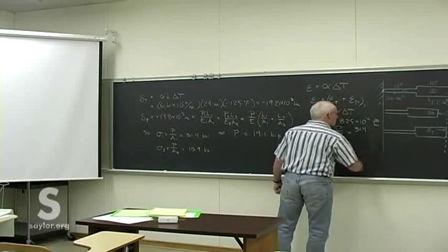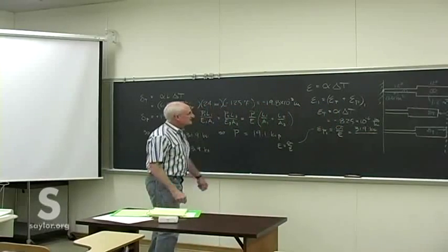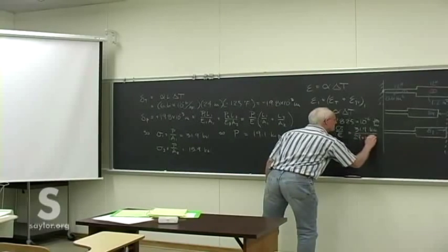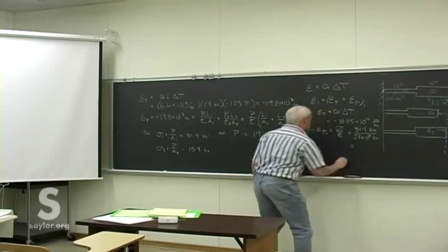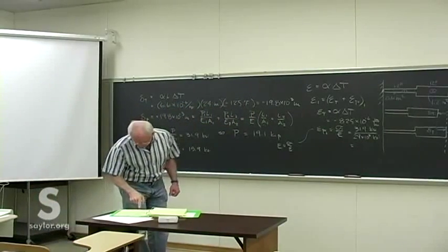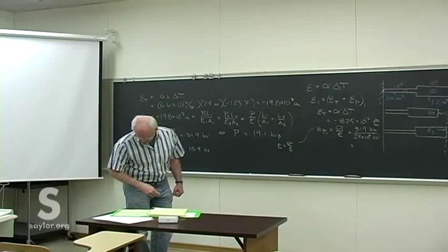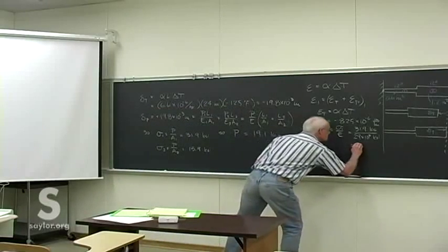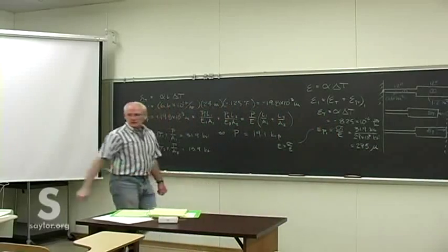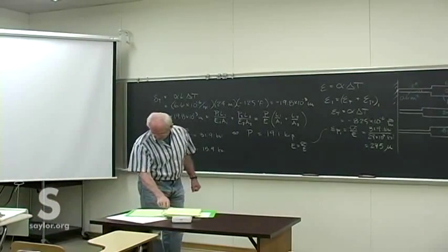I did have that right. And Young's modulus, oh, we had it, I erased it. 29 times 10 to the third KSI. So the mechanical strain in the first one is plus 275 times 10 to the minus 6th. Just to remind you, we also often took out the 10 to the minus 6th and just put in the symbol micros, micro inches per inch.